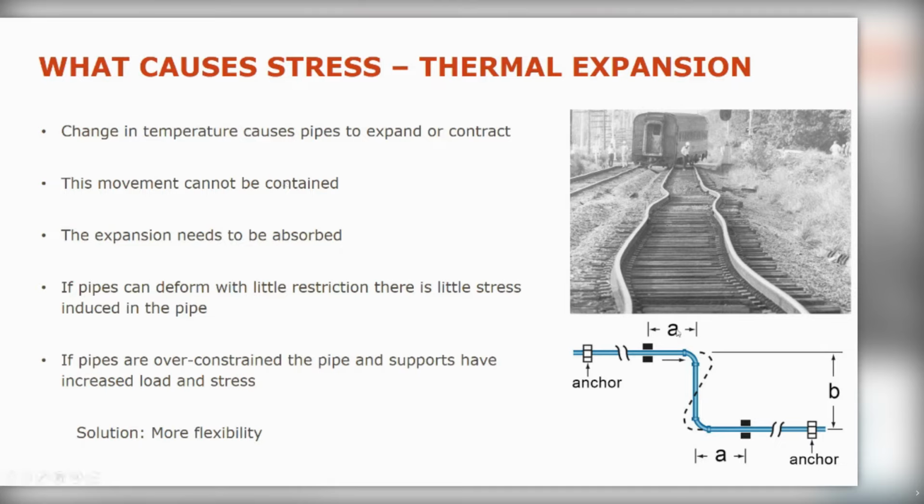If you look at the little graphic at the bottom, that illustrates the point quite well, where we have a couple of pipes. Look at the longitudinal direction. This will grow and it will push into this direction. It will create that sort of zigzag in the pipe. This is an over exaggerated shape, of course, but it just gives you an idea of how it will push. So the important thing is, this elbow has to be able to move in that direction, and this elbow has to be moving in that direction.